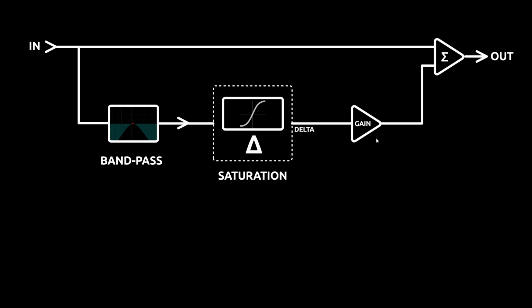And using the delta signal works particularly well with nonlinear or level-dependent effects like saturation or compression or clipping. If you have a plugin that strongly affects the phase, then those are often better used in series. An easy way to check for this is to listen to the delta signal and hear if it can get completely silent apart from the added effect.